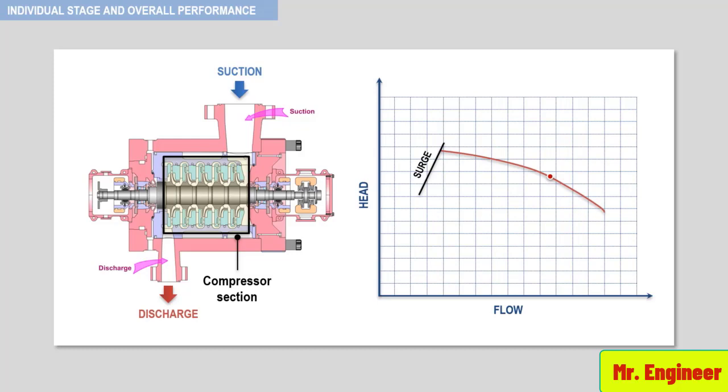Remember that each gas composition requires a different amount of head to increase its pressure level to a given amount. An impeller or blade is designed for only one gas composition, and therefore only a specific amount of head is designed in a blade or impeller for a given application at a specific flow rate.